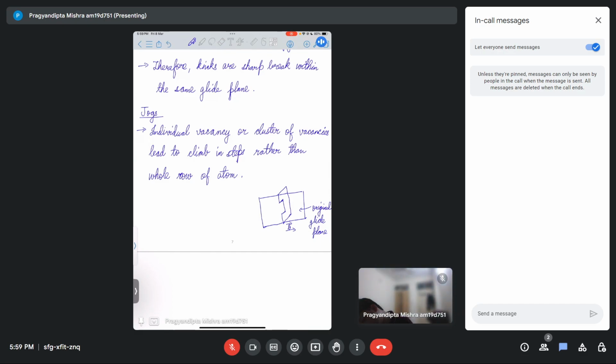So I have the new disconnected portions of dislocation as L, this as M, and this is N, right? Like last time. Now I can write for L. For L, I can write the Burgers vector is perpendicular to the dislocation line, right? So the L part is similar to the original dislocation where there was no change. Even the N part is the same, right?